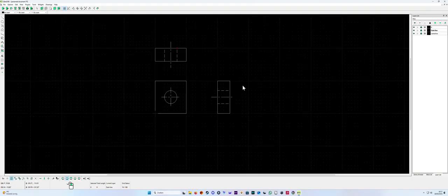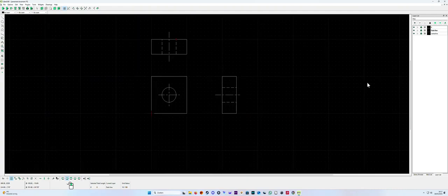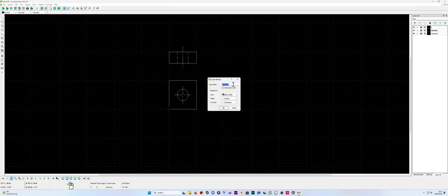And then you must put some measurements inside. So let's do some measurements. I always say measurement lines, and always 0.05 thickness. You can do it thicker, but you must always keep the drawing lines thicker than the non-drawing lines. So the center lines must always be thinner. I nearly always use 0.05, and also continuous.